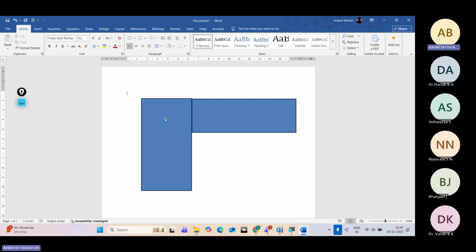So to model this in ETABS, you can use the insertion point. Now, if it lies within the minimum eccentricity as prescribed in the IS code, then you do not need to model the insertion points. Otherwise, you'll have to do it.